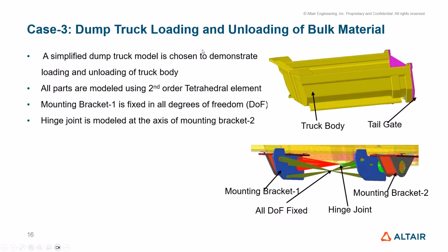Here all the parts are modeled as first order tetrahedral elements. The bottom parts considered for the numerical simulation of EDEM plus FEA co-simulation are the mounting brackets, because we need to consider certain additional parts to avoid localized displacement and stresses. That is where the extension to the underbody, truck body, and these mounting brackets is considered.